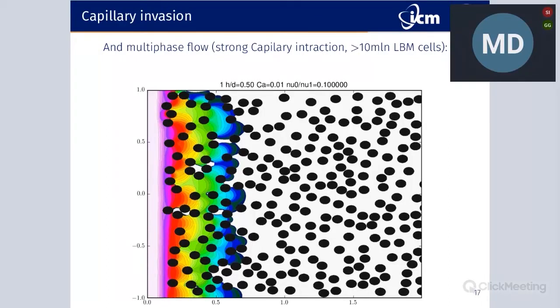case where there's high capillary interaction, so the shape of the front is strongly capillary dominated, and the front is transferred not in a continuous way, but in a series of jumps that are often quite rapid and linear. So this is like going from one stable configuration to another. This is not a very desirable situation, and there is a high pressure to overcome if you want to move the front to the next step.